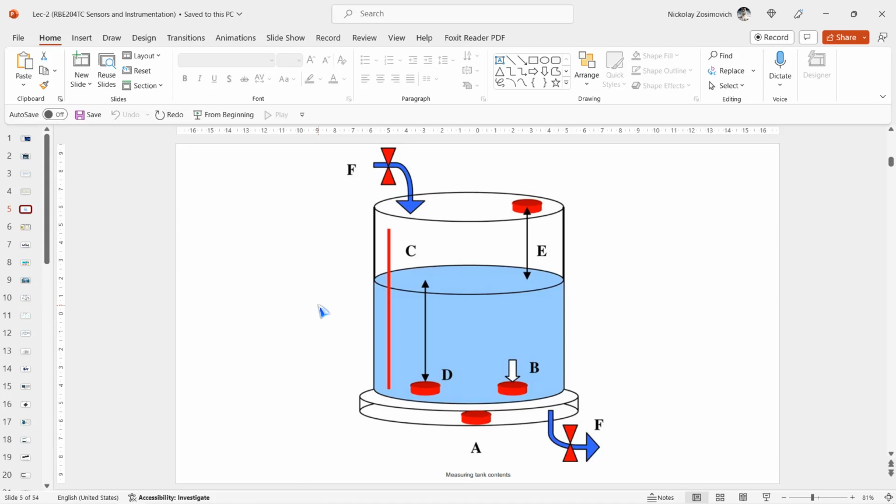For instance, if the tank contains a corrosive fluid, a non-contact measurement principle is preferred, right? Putting principles B, C, and D on a lower position in the list. And further, for very large tanks, method A can possibly be eliminated because of its high cost, right? The conceptual design ends up with a set of principles with pros and cons, ranked according to the prospect of success.